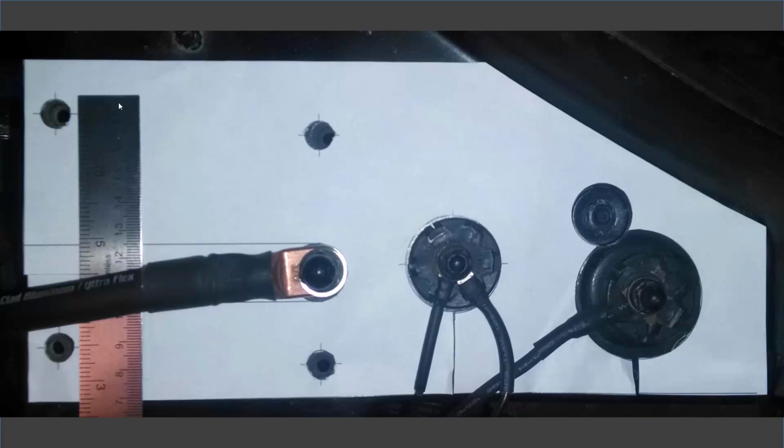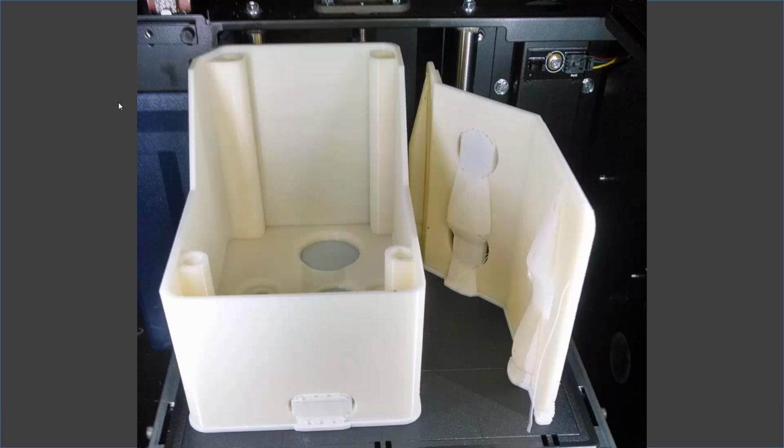Something I'm doing more and more is printing out 1:1 templates for things. So I modeled this up. I printed it in the Uprint. This is how I printed it, the orientation. What I was looking for here is, one, I wanted to fit it all in one build tray so I could run it overnight. But two, I wanted vertical surfaces, because vertical surfaces give you the best surface finish.